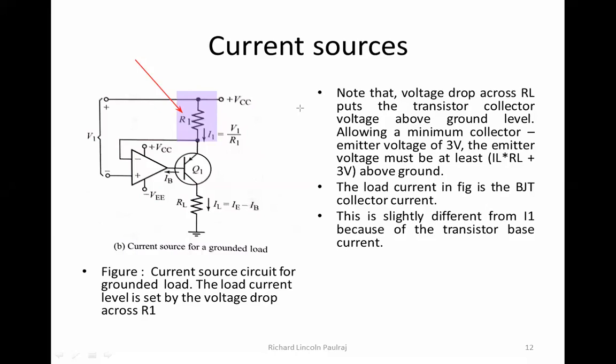Even though this transistor is helping in driving, it needs a supply, right? So the supply is created with the help of the input voltage and R1. So R1 is a key factor here because I'm going to keep my input voltage constant. So I'm going to vary my R1 based on the levels of currents or voltages that have to pass into the BJT.